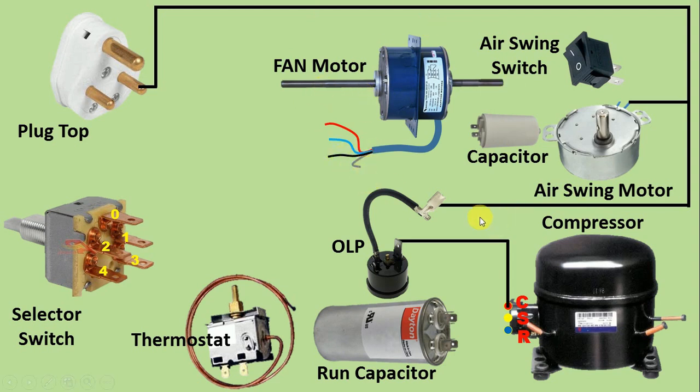So what we will do, from here connect a wire, and with grey wire connect this wire. That is, with the wire which is of neutral connect this wire. On this fan motor, here you can see a diagram is there. By referring to this diagram also, you can do the connection very easily. So friends, connection of neutral power supply is completed.